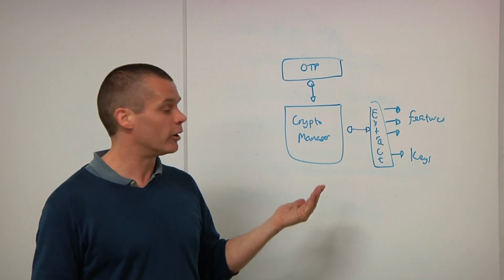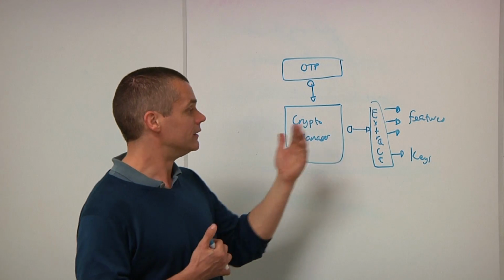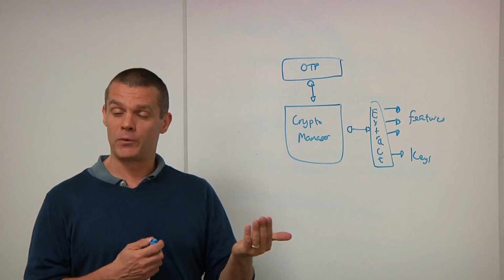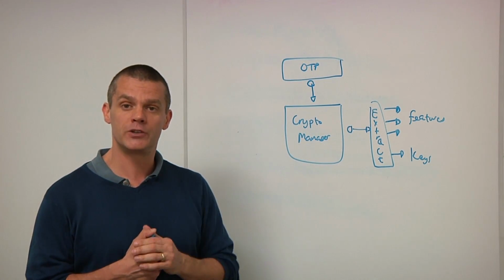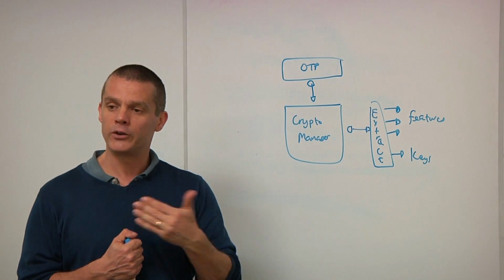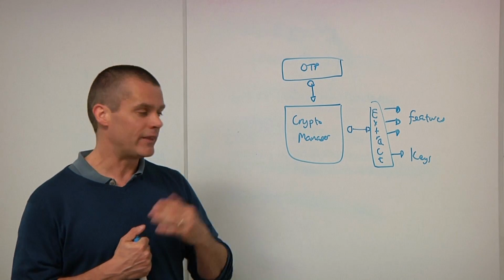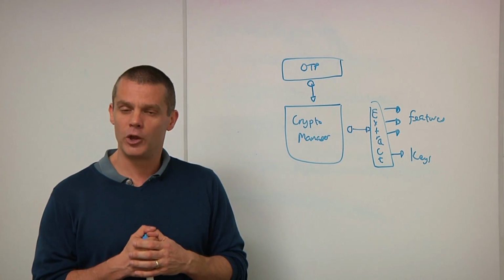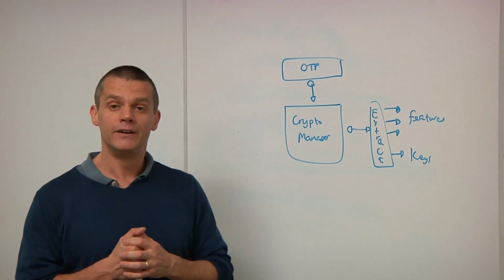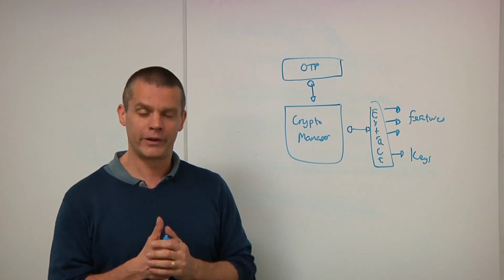So we've talked so far about using it for security, but let's talk about using it for features for a second as well. What we see now is chips getting more and more complex, and chip makers with a desire to tape out fewer and fewer chips because of the cost. So what they've done in the past is make one chip with a number of features that can be turned on and off via OTP. And that's great, but as the number of features that you want to enable grows, you start to get limited by the amount of OTP you have. It's also something where you can only turn the feature on and off once because of the nature of OTP.